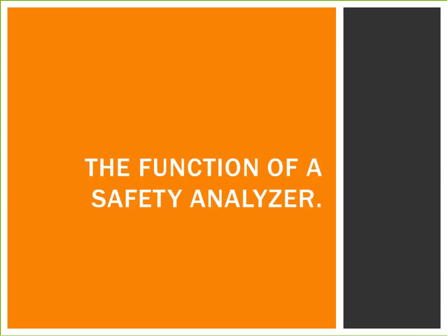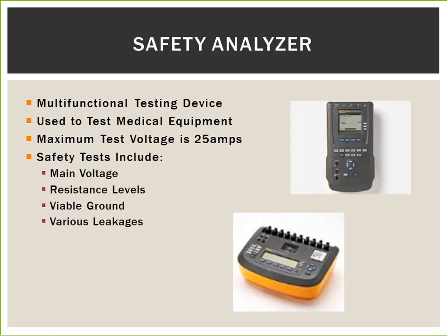Next, we will cover the function of a safety analyzer. A safety analyzer is used by healthcare professionals to perform electrical safety testing on medical equipment both in the field and in facilities. This multifaceted test instrument performs all primary safety tests, includes main voltage, protective earth resistance, insulation resistance, device current, earth, chassis, and patient leakages, as well as several additional leakage tests.